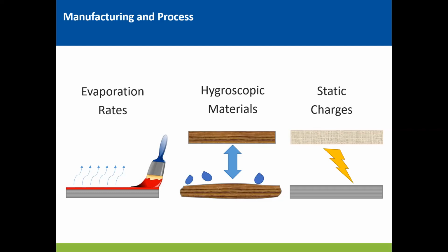And what tends to happen with these materials is when they're exposed to dampness, they'll absorb the moisture, and that will tend to drive a change in the structure of the material. The moisture molecules are getting into the molecules of the material, and they're going to start pressing outwards. And this is where we get dimensional changes that you might see with wood. If you've ever left a piece of wood in a puddle or it's gotten wet, you may notice the warping effect that can happen. Conversely, when materials like wood get too dry, they lose all their moisture, and then they're going to tend to shrink and lose a lot of their volume.